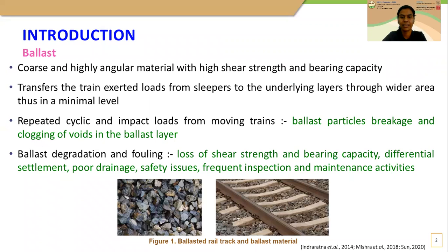Ballast degradation and fouling lead to loss of shear strength and bearing capacity of the ballast layer, therefore differential settlement, and it leads to poor drainage and it creates safety issues. Therefore, there is a need for frequent inspection and maintenance activities.